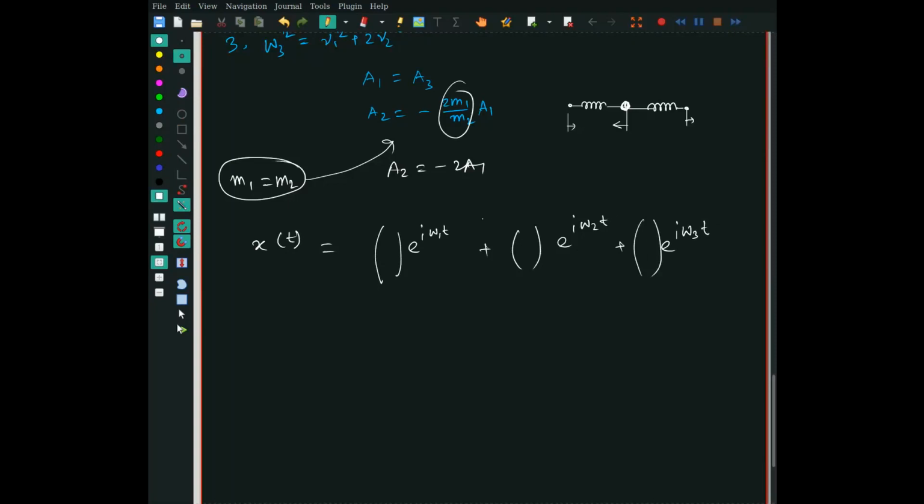So remember for the first mode of oscillation, a1 equals a2 equals a3. So I have basically 1, 1, 1 here times some normalization, that is n1. For the second mode, I had 1, 0, minus 1 here times some normalization constant n2.